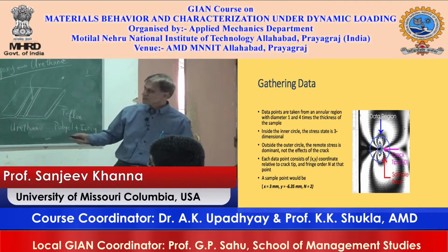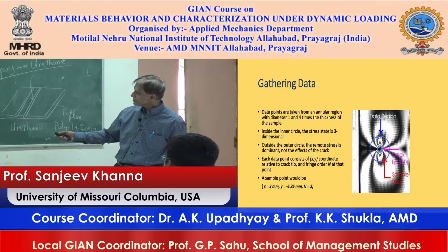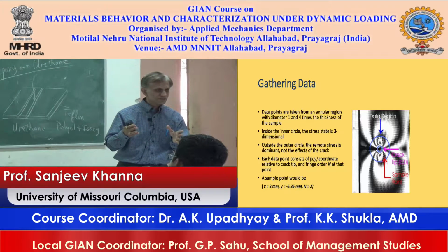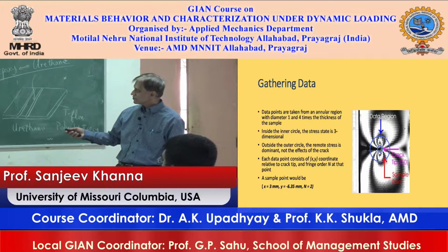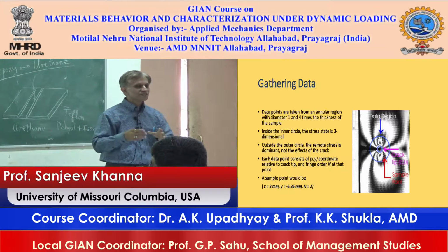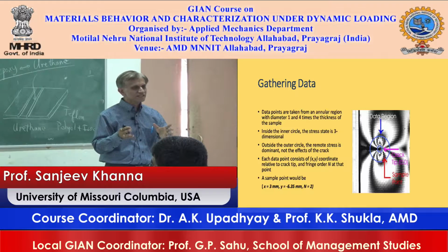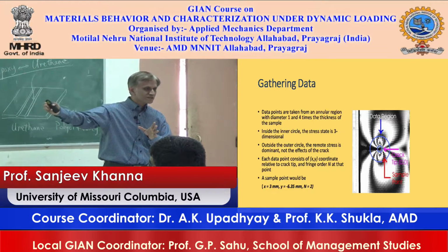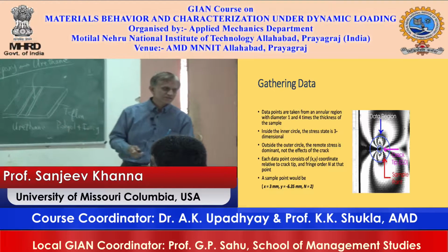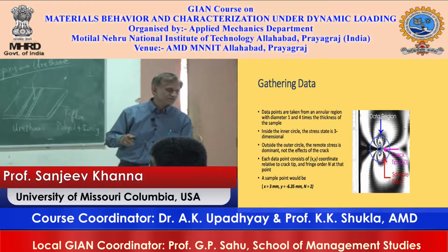This outer circle here has a diameter of about 4 times the thickness. We believe that outside of this, it is too far from the crack tip, so it is not the singularity dominated zone. It is dominated by the far field stresses, not by the crack tip stresses.